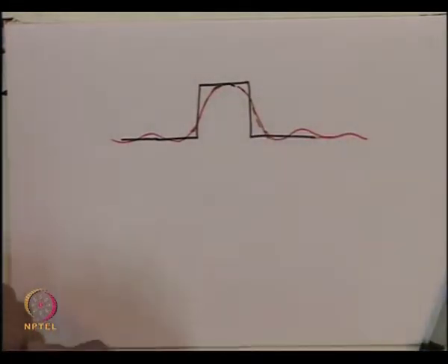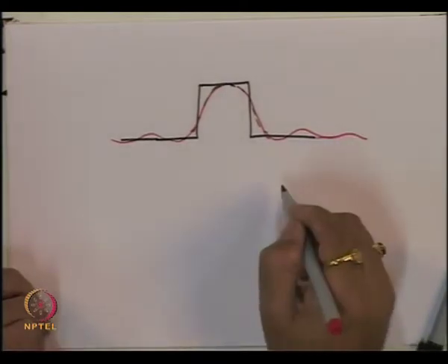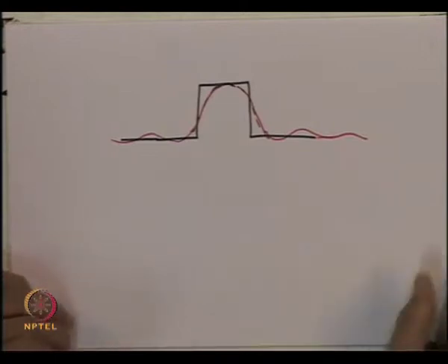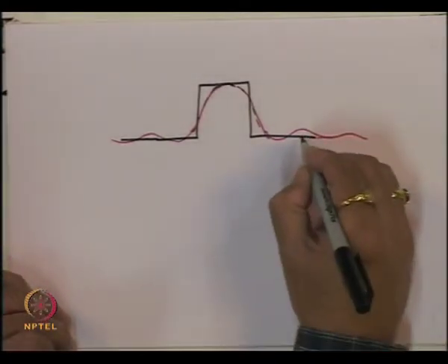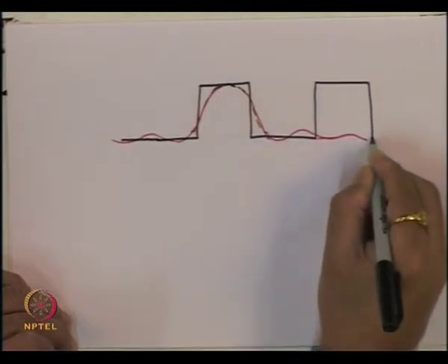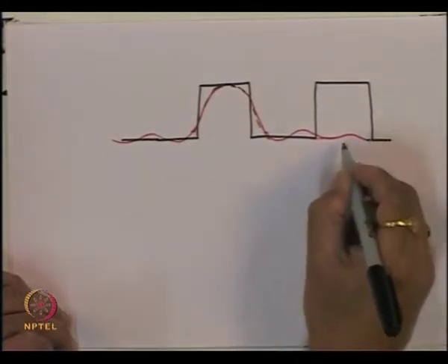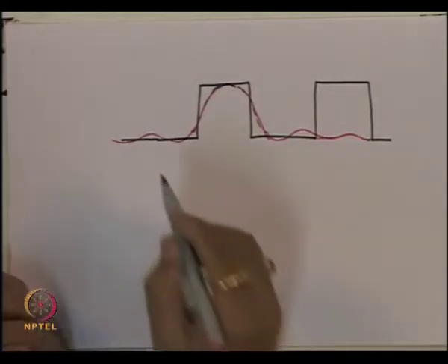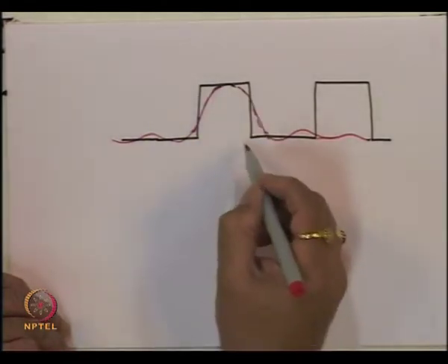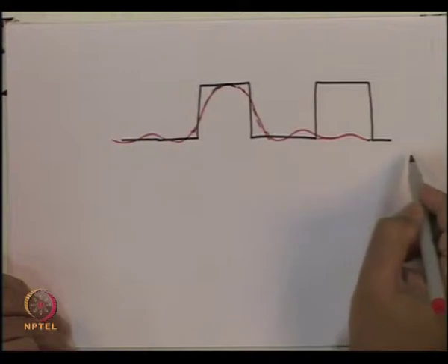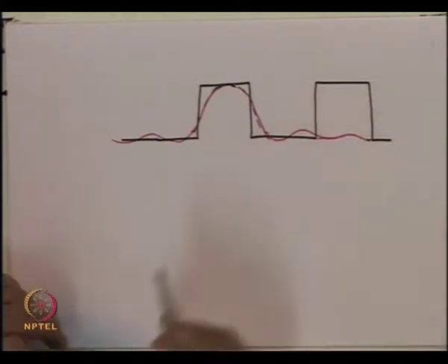Obviously, this signal which ideally should have been 0 now is having these fluctuations. So, if you have another bit present at this location, this signal is going to superimpose on this. This phenomenon is what is called the inter-symbol interference. So, we are transmitting this bit, and this bit is now going to create an interference at another bit which is separated in time.